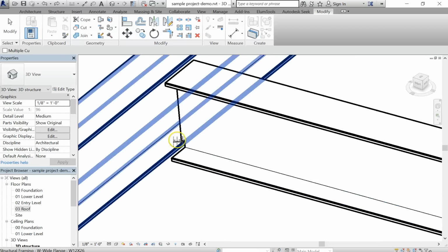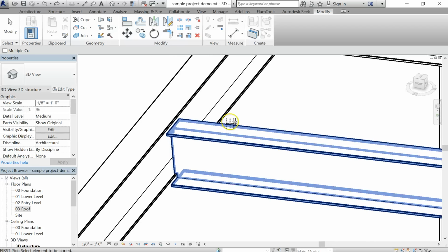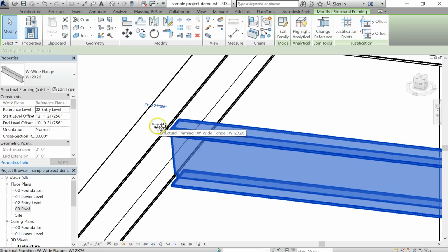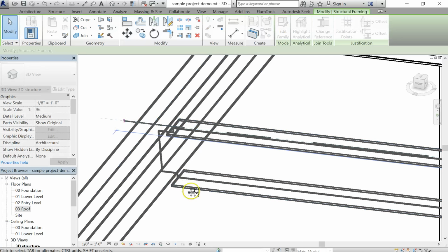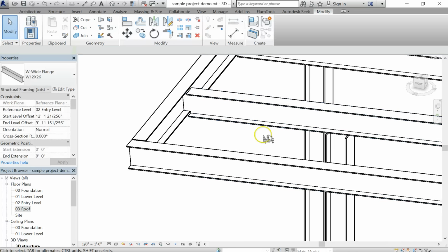And you'll see when I use it without pulling the beam through, it's not actually going to get all the way to that adjacent beam's web. So you normally want to just click on the beam, grab its little pull point, and stretch it over so that they can make their connection.